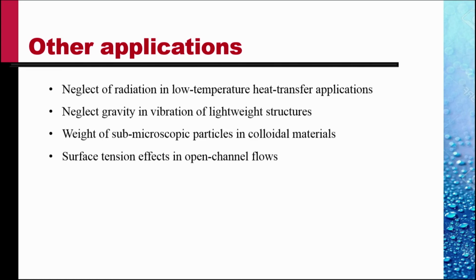Surface tension effects in open channel flows are not considered. This is an important application, and we'll consider this later in more detail, particularly because it exposes a new paradigm. There are situations when surface tension is negligible in the prototype, but could have serious consequences in the model if the model is not made carefully. We'll discuss this later.